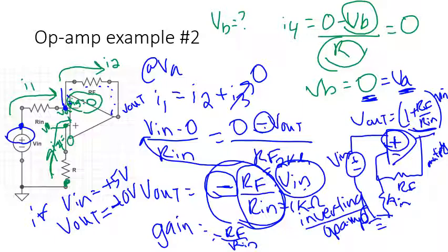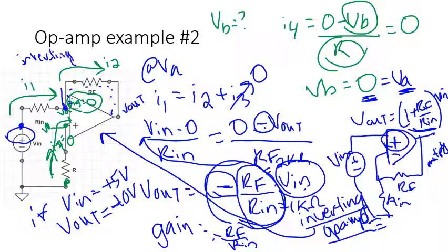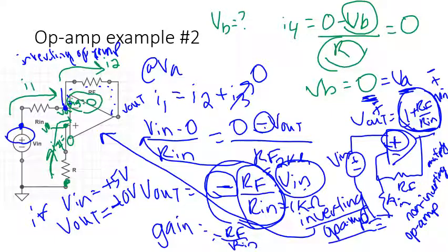Okay, this is called an inverting op-amp. Our first circuit we just had on the previous slide is called a non-inverting op-amp. I can't write well with this pen now. Why is it non-inverting? Well, because I don't flip the sign here. It stays the same sign. If Vn was positive, then Vout's also positive. Vn's negative, Vout's also negative. Here, I do flip the sign because of that. So those are my differences with it.